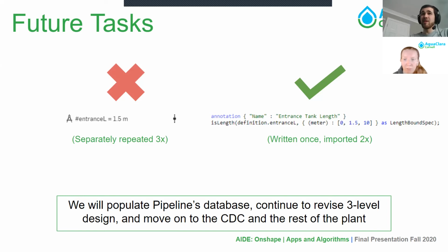So for example, currently we instantiate variables called expert inputs and then enable them to be overridden by creating several individual variable features and then importing them all. This works, but it means that we need to repeat the same code in 3 places. So we plan to make this process happen more efficiently by using FeatureScript to create a single list of these variables to be directly imported into the build feature and the hydraulic design function code.